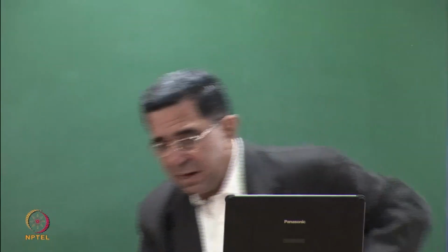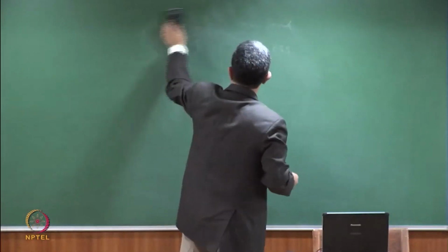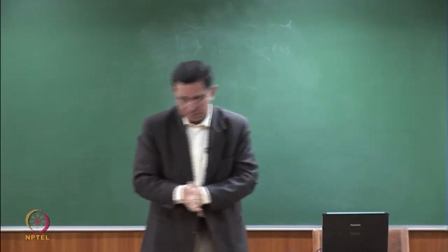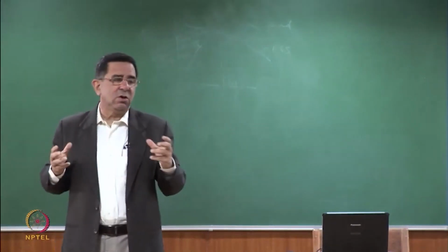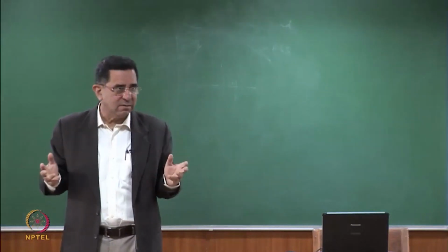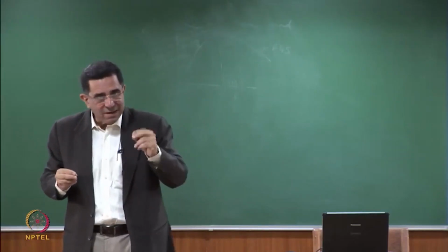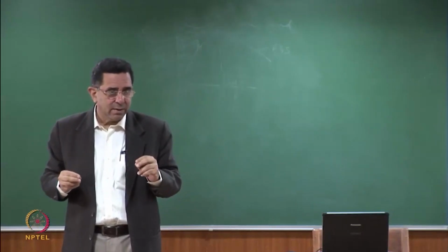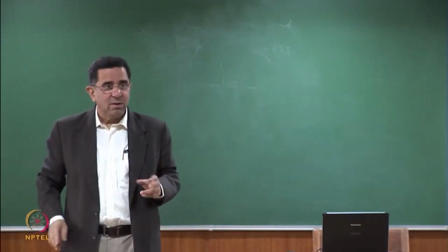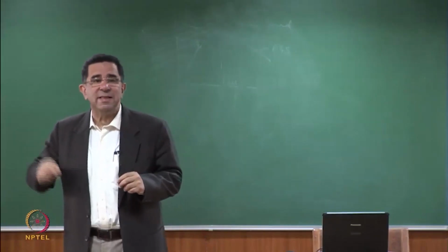So let's just quickly summarize a brief comparison between ash and tailings. Before we do the summary, are these hazardous? Are mine tailings hazardous? Well, the original ore from which they come is rock, which is not hazardous. Now there are two components to it which are a problem. One is the problem of the metal, right? And the other is the problem of the chemicals that have been used to extract the metal. So tailings can become hazardous if they have a lot of metal remaining in the end.